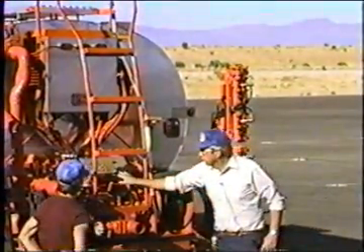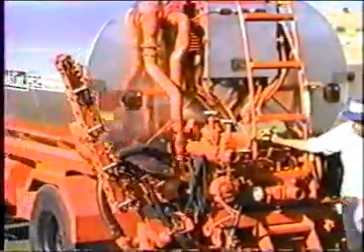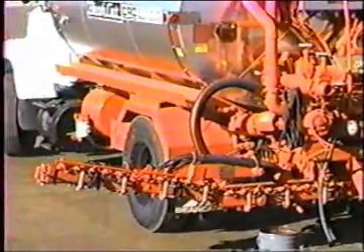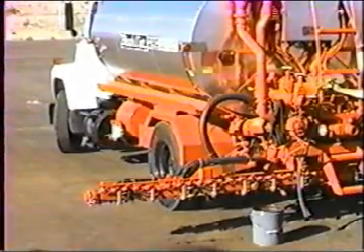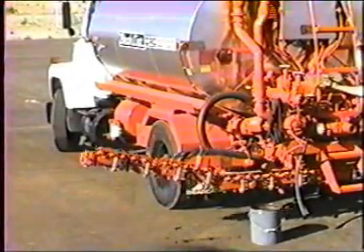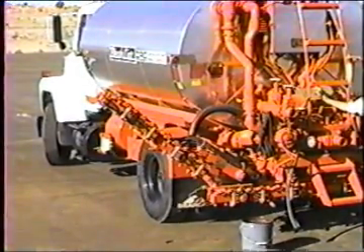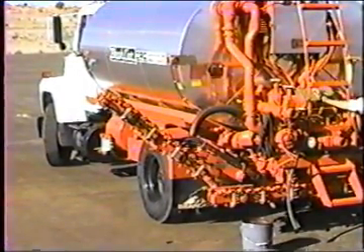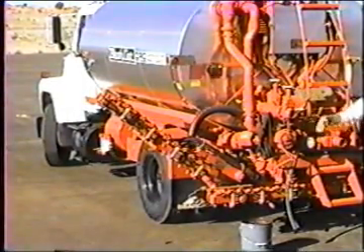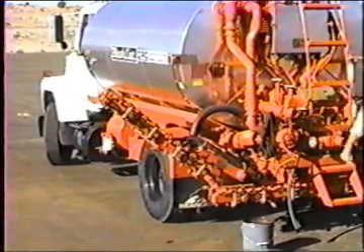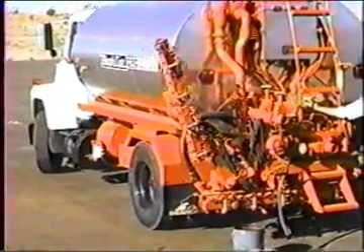It'll go nearly down. I'll do it on that side so Bob can see it there. When I put that wing down, if it were all turned on, nothing would happen until we got to about that point there, and then it would turn on. Now it'll continue to spray. If I pick it up, it'll spray up to about that height before the mercury switch turns it off. The reason for that is, if we wanted to spray a bank, or widen our spray out just a little bit to catch a place we missed out there in the middle, we could do that. When we go on up with it, it would turn off.